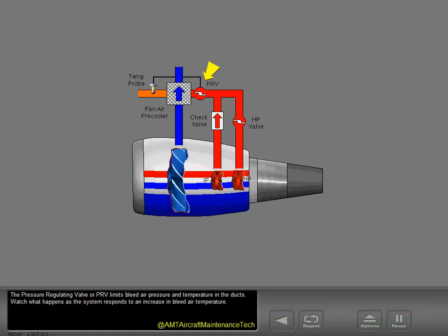The pressure regulating valve, or PRV, limits bleed air pressure and temperature in the ducts. Watch what happens as the system responds to an increase in bleed air temperature.